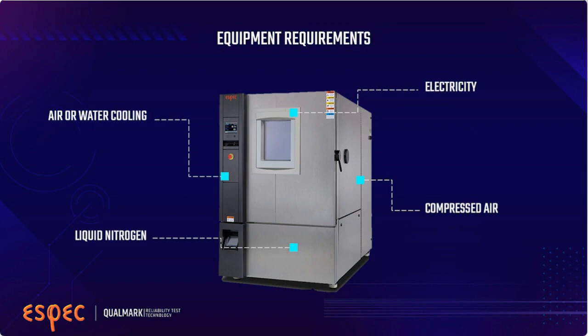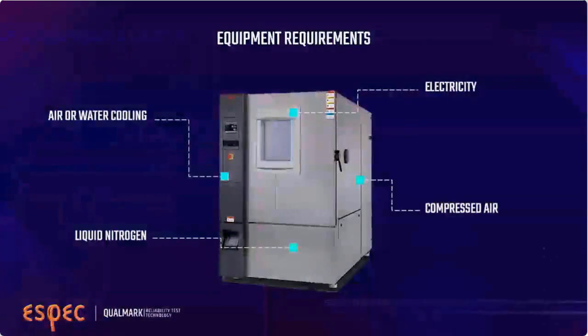The thermal cycle chambers use the refrigeration system to move the heat out of the chamber, and it needs to go somewhere. Air-cooled chambers ventilate the heat directly to the air. Smaller systems can do this in your lab space, if the room can absorb the heat generated. Otherwise, the heat is released outdoors with an air-cooled condenser, kind of like you'd see outside a restaurant or a grocery store.